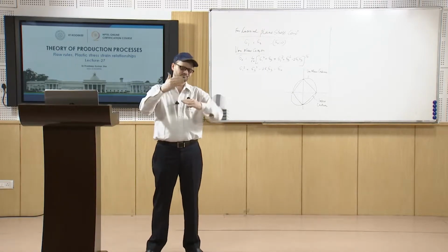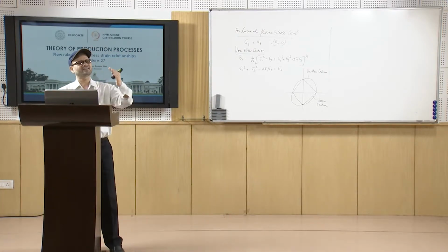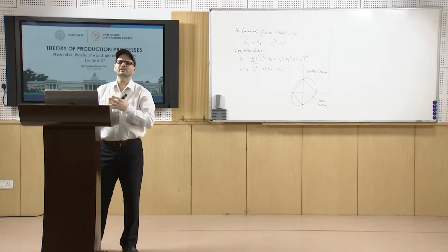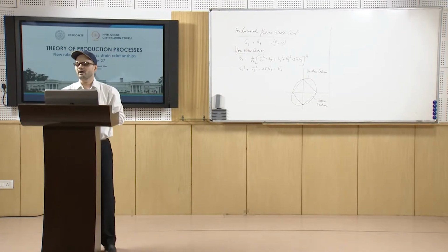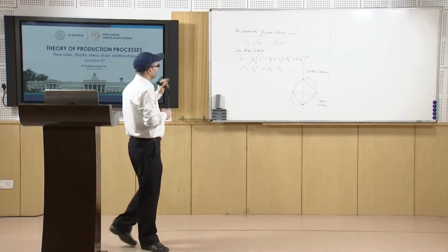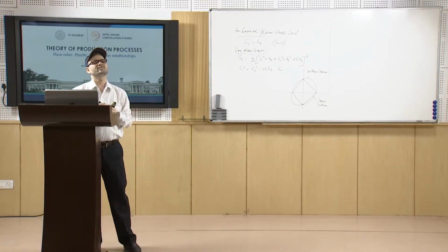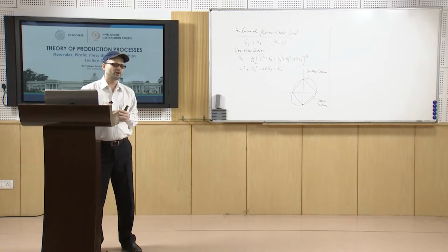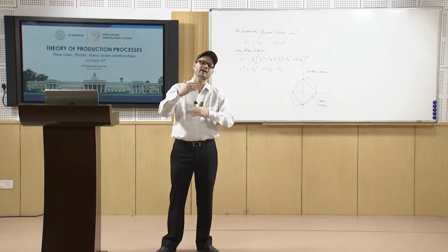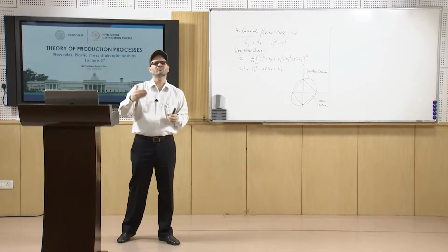That is very unique, that they make equal angles with all the principal directions of the stresses. Because of that, the octahedral shear stress or octahedral shear strain plays an important role. Basically, if you talk about the octahedral shear stress concept, you will see that it is the stress equivalent of the von Mises criteria.